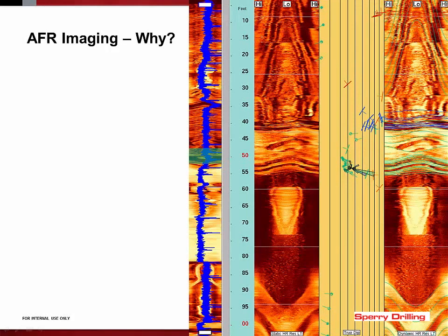The tool in question is the AFR, the Azimuthal Focused Resistivity tool. The main function of this tool is as a borehole imager, providing very high resolution images of the borehole like the one shown on the screen. If you notice the depth scale here, this is only 5 feet between depth markers. You get a sense of the high resolution of the measurement that this tool can provide compared with some of our other tools. Just to give you a sense of scale, this is something like 10 times better resolution than any other measurement that's available on LWD at the moment.